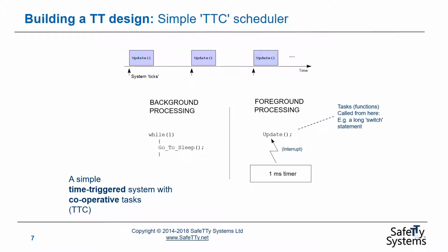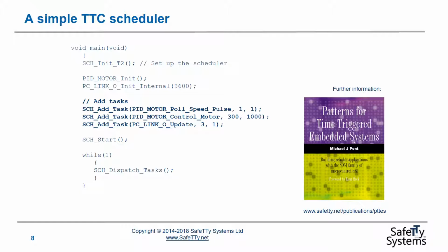In practice, we probably wouldn't build the system this way, certainly not for a safety-related system. In practice, we'd use some kind of simple task scheduler. And this would give us a cleaner way of adding tasks to the system with an appropriate interface. I'm not going to discuss in this video how we would create a task scheduler.